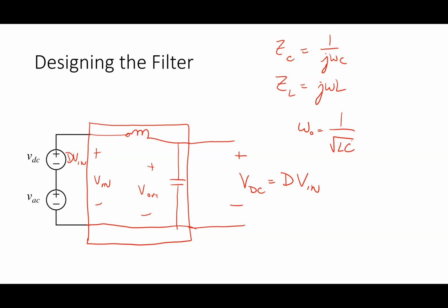So basically what this is saying is I've got to make sure that the frequency of this guy here is a lot faster than whatever the cutoff frequency of that filter is. In hertz, because it's easier for me to think in hertz, 1 over 2 pi square root LC needs to be much less than 1 over T, the frequency at which I switch this thing. A common thing to do, like in your motor drives, is a couple of kilohertz or something like that.